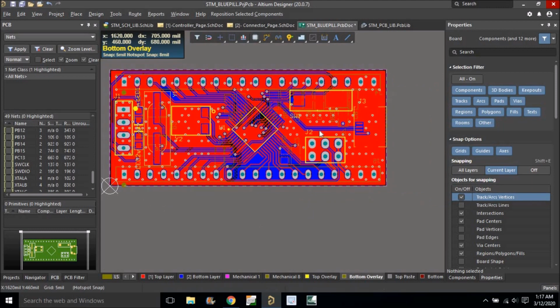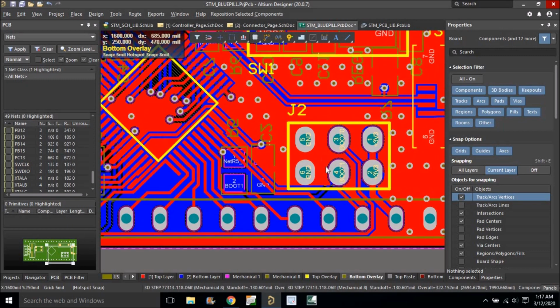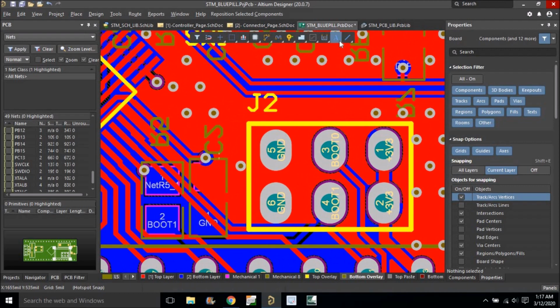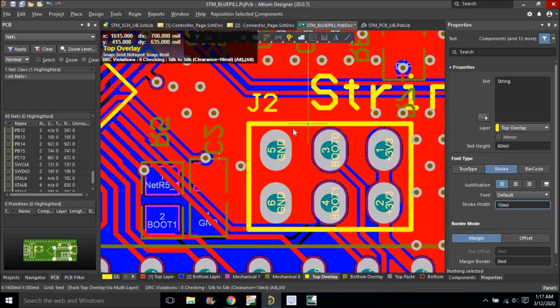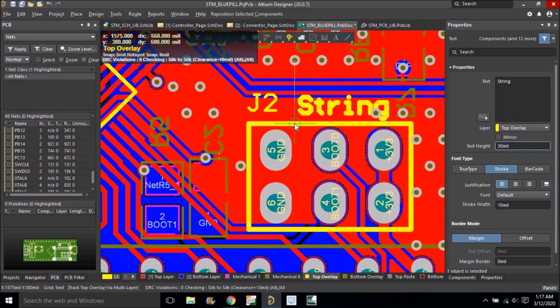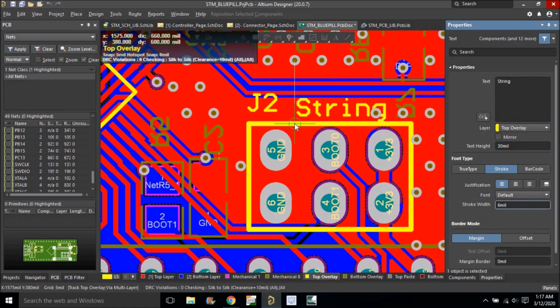Now we're going to name this board. We'll place the board name, and we'll just name this thing also. So what we'll do, we'll just select the top layer and string, tab, change the value to 30 mil, tab, and make it 6 mil, this thing.